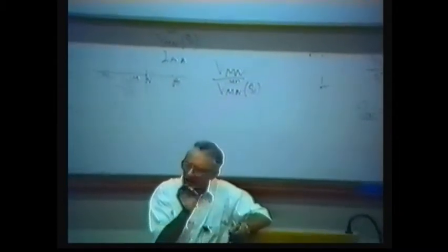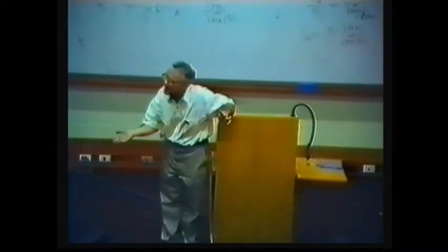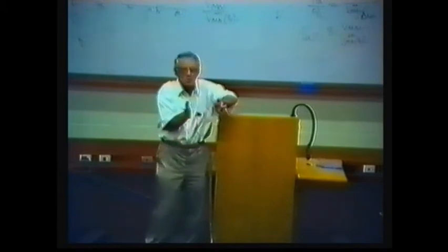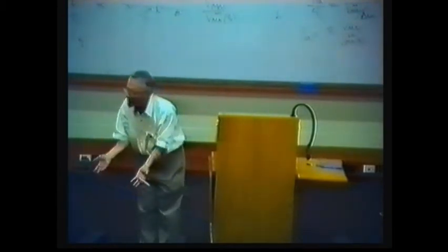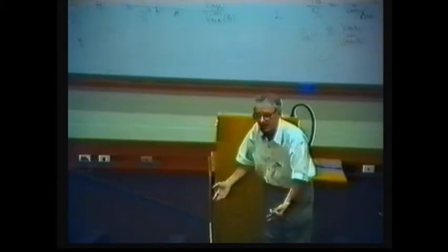But before, let me tell you, this transformation from real signals which we measure to apparent resistivity doesn't add or subtract information. It's pure arithmetic. So we have the same information in the field which we measure and in apparent resistivity.